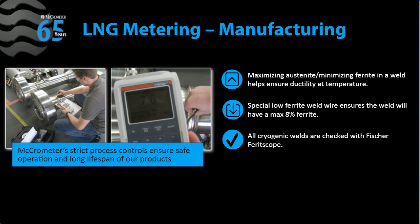And just to go into a little bit more on the manufacturing, when it comes to welding these types of meters, we ensure that we are maximizing the austenite and minimizing the ferrite in the weld so that we can help ensure the ductility at these negative temperatures. We also use special low ferrite weld wire so that the weld can have a maximum of 8% ferrite. And then at the end, all of the cryogenic welds are checked with a Fisher ferrite scope.